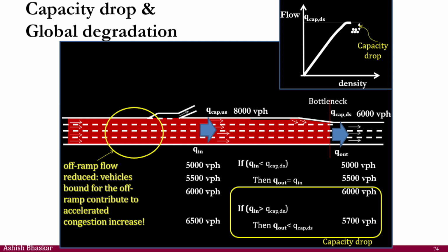If I divide this whole road into different cells, then I will have certain characteristics of my fundamental diagram here compared to the other one. The diagram I've shown here is for this point, the diagram for that one might be different, and for some other place it will be different. I will show you those for the entire stretch of a motorway section, how the shape really changes. But yes, you have to understand the traffic behavior there to do that kind of modeling.